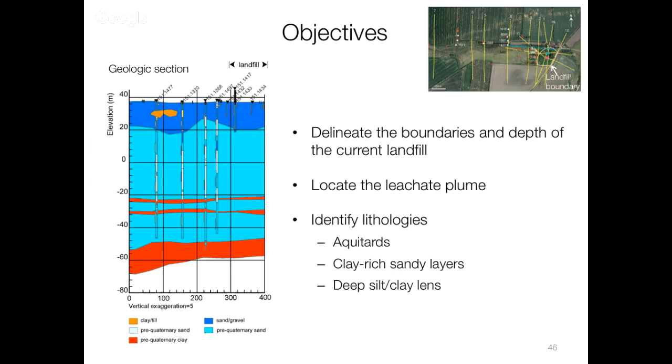So those are the objectives. There's two of them, actually. The first is, okay, where is the landfill? What are the boundaries? What's the depth? I mean, how much waste can we find? And associated with that, there's this leachate plume that's going through, so you want to delineate that. That's really the thing that people usually consider when they're talking about landfill problems.